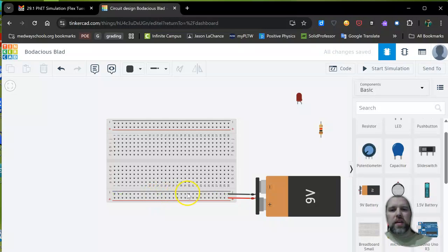As I was saying, the whole row lights up because this whole row is connected on the back side. So anywhere you put a wire here, it's like connecting to the same spot. Likewise, all of the columns here are connected as well. Any of these 1, 2, 3, 4, 5 spots are all connected together. Nothing's connected across the middle, so these 5 are independent of those 5.